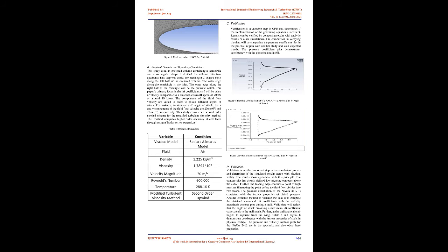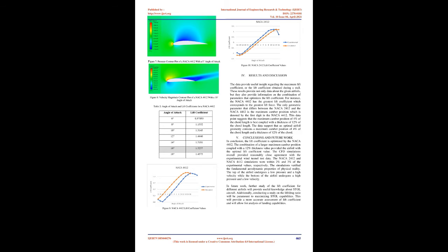This study will conduct a 2D analysis on the airfoils using ANSYS Fluent. The first step of running the simulation is sketching the 2D airfoil by utilizing an airfoil plotter. The plotter on airfoiltools.com allows the user to specify chord, radius, and thickness to create an airfoil. The plotter also has preloaded NACA airfoils. The airfoil can be saved as a list of coordinates and inputted into ANSYS to create the airfoil surface.